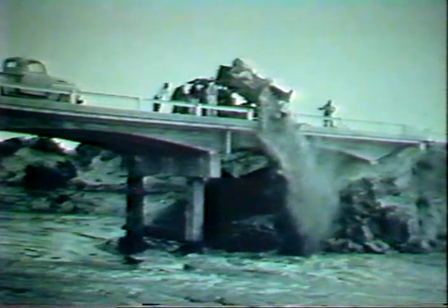Encroachment of abutments on a channel may cause flow constriction during a flood and consequent bank erosion by eddy action downstream from the bridge. At this bridge in Nevada, rock riprap was dumped into the area eroded during a flood in 1952. The flow direction is from left to right.